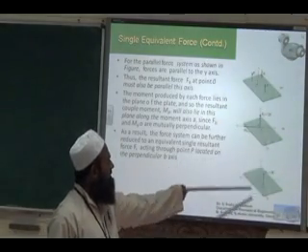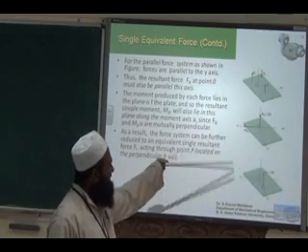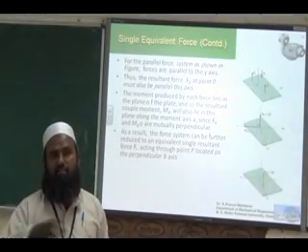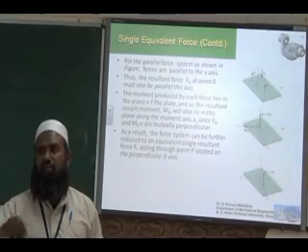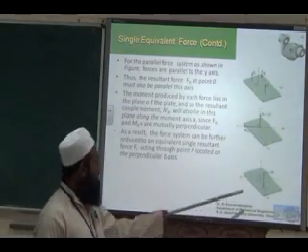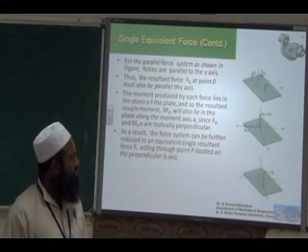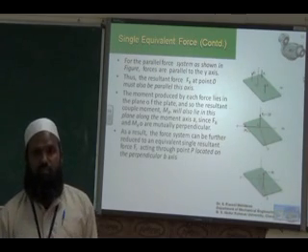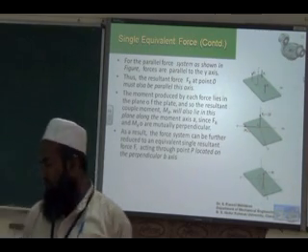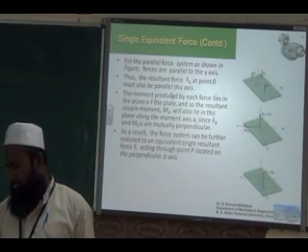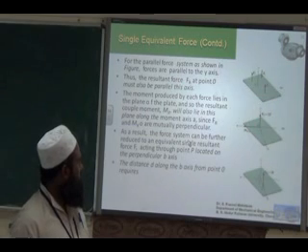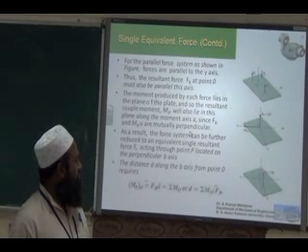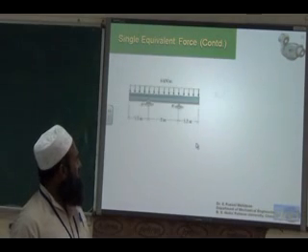One axis is parallel to the force direction. The other axis is the one about which the resultant moment acts. Perpendicular to the two axes, we have to consider the third axis and consider the point of action of the force at the distance D. Okay, so this will be equivalent to the first system. So these are the three cases we have. Either it may be concurrent forces, or a coplanar system of forces, or a non-coplanar system. So D can be found by D equals sigma Mr by sigma Fr.